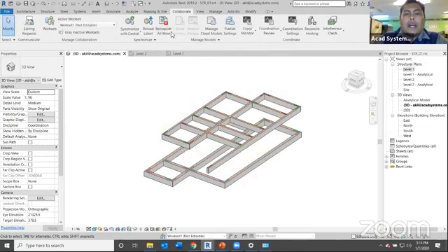Okay, and then if you have everything sorted out, you can simply synchronize with Central. That means it will synchronize with Central for structural. So it says here the STR1 is the central model. If your team is linking with project Revit links, so many layers of linked Revit, you can still work on this platform because it won't stop you from linking, and whatever you do in these projects will stay synchronized with Central, even though that file is not really the actual Central file that you work with.